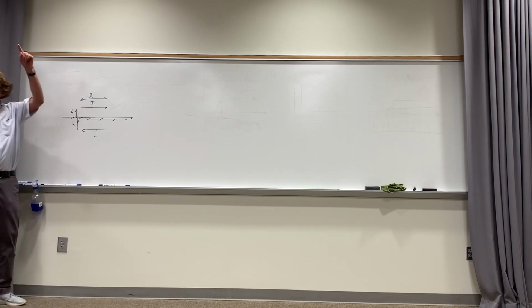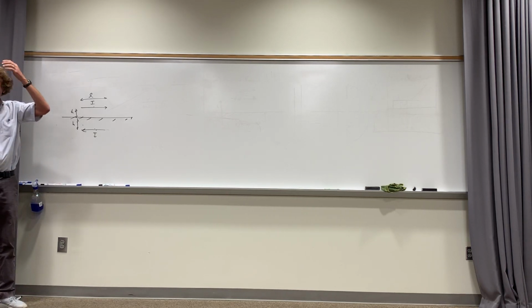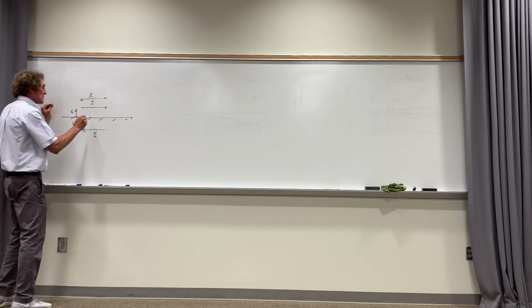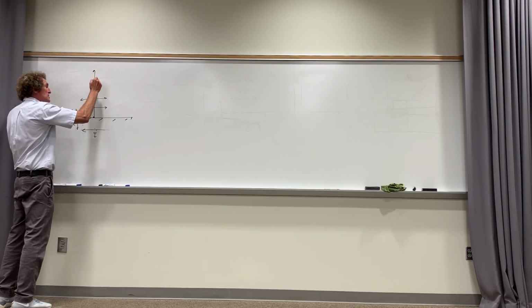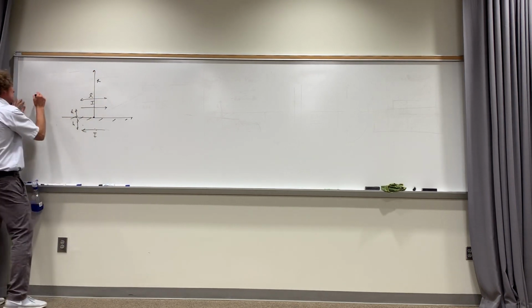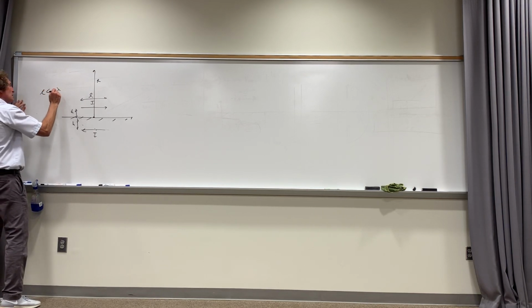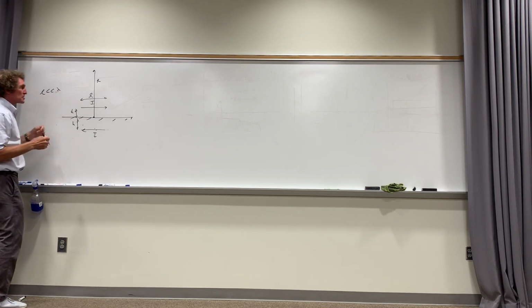It's not like the dipole antennas where the image on a monopole creates the dipole fields, right? Here, what you need to do is, let's just get the electric field from a center point out here, a distance r away, and assume L is much, much less than lambda. So this is a short dipole.